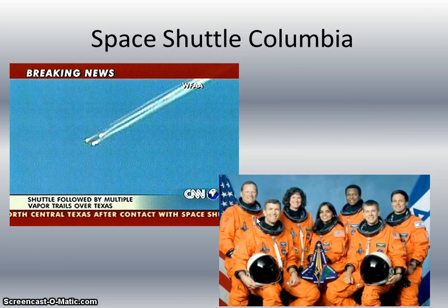In 2003, the Space Shuttle Columbia had a problem with their thermal protection system. It was damaged during the launch of the space shuttle a week and a half earlier. As they came back into the atmosphere, the incredible heat built up, and where there had been damage done to the thermal protection system, that heat weakened it even more and caused it to what's called zipper or unfurl. And unfortunately, the entire crew was lost because of a failure in the thermal protection system.